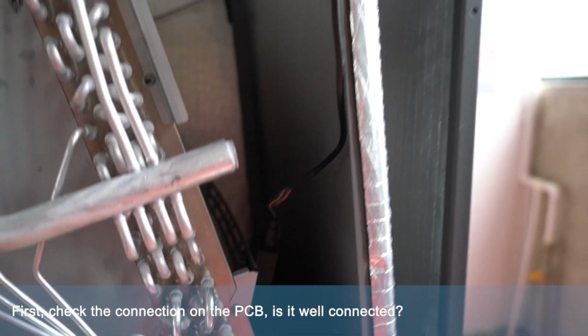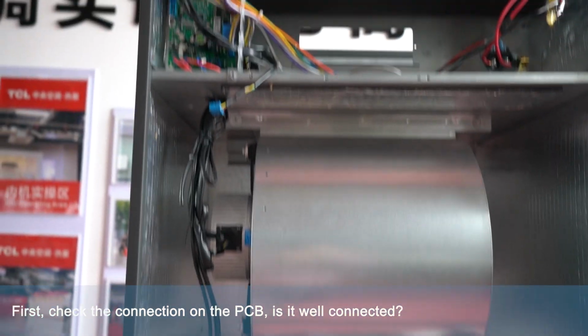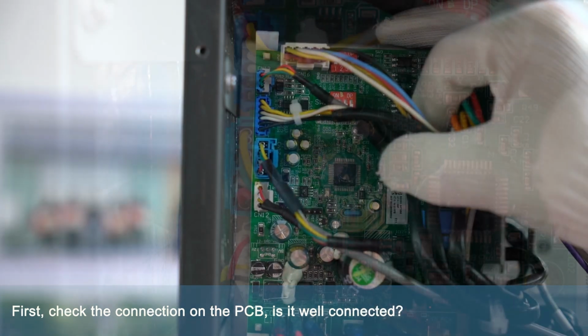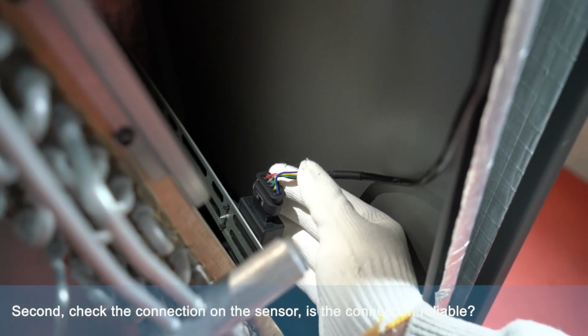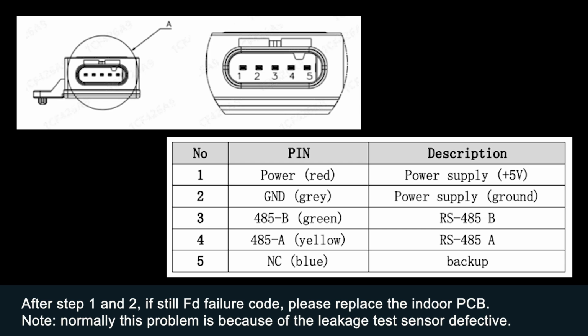First, check the connection on the PCB. Is it well connected? Second, check the connection on the sensor. Is the connection reliable? After step 1 and 2, if still FD failure code, please replace the indoor PCB. Note, normally this problem is because of the leakage test sensor being defective.